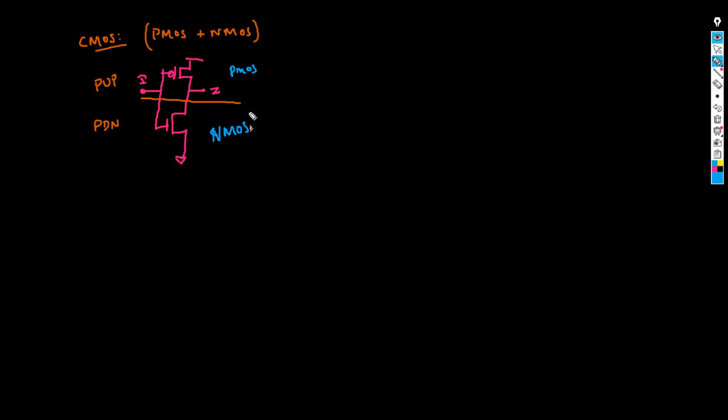Okay, now how is it possible? In this case, when you give zero, what happens? What happens to your PMOS? PMOS is on, and NMOS is off. Okay. And then when you give 1, what happens? PMOS is off and NMOS is on. Now this is basically how the circuit operates.